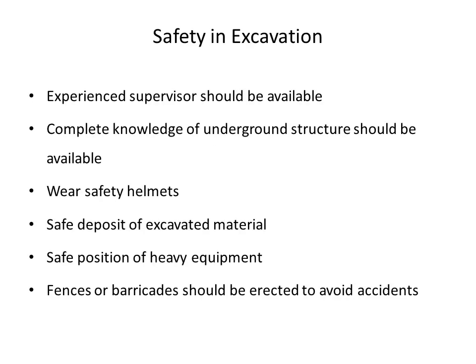So how will we ensure the safety in excavation? In order to ensure the safety in excavation, an experienced supervisor should look after the excavation work. And also, before going to the excavation, a complete knowledge of the underground structures should be available with the workers. That is, any sewers, pipelines and other underground structures passing below the soil should be known.